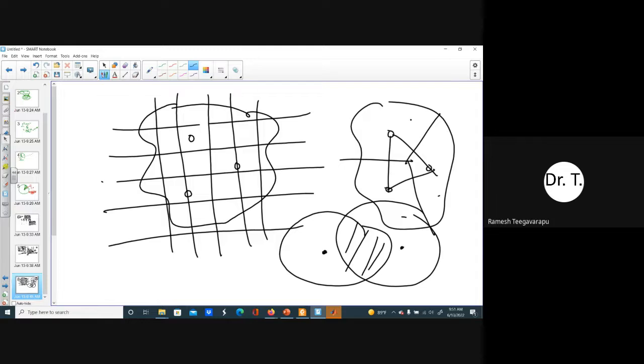Now, having said that, you might say, well, a lot of countries are still using rain gauges. They are able to succeed in developing flood forecasting models. Yes, you can still do that, but the adjustment happens in the calibration. So now the calibration is overtaking the issues related to the rainfall values which are provided spatially within a distributed hydrologic model. So you are taking the lumped input and converting it into a distributed input.